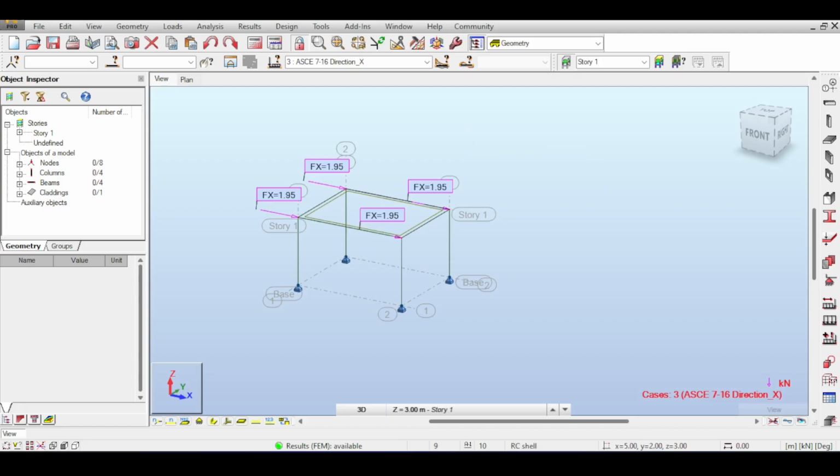Now, what's the idea behind that? Technically speaking, I understand that W is the dead load and the self-weight, because when a structure is going to start vibrating, those dead loads and weights are going to be included in the mass that vibrates. But why include live load? You include live load because when the structure starts vibrating during an earthquake, usually there are some people inside the structure, and those people have masses, and the mass is included in all the inertia forces. So some codes do require you to take parts of this live load into account when calculating your seismic loads.